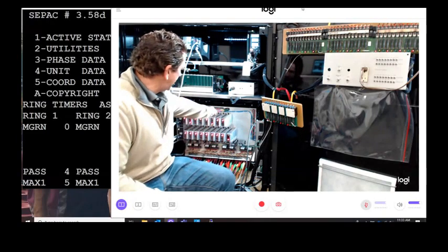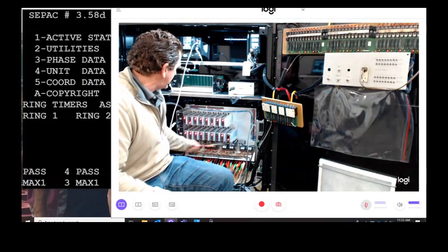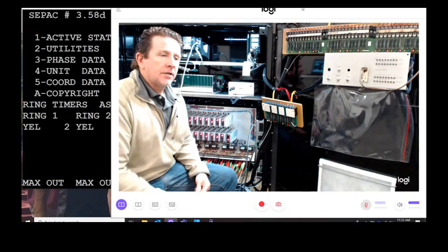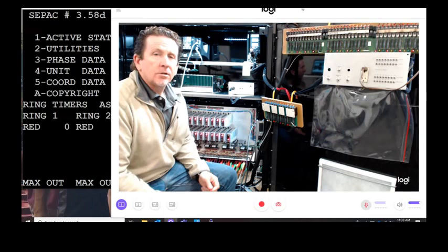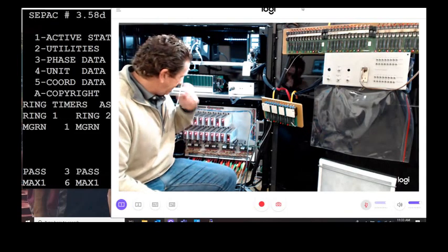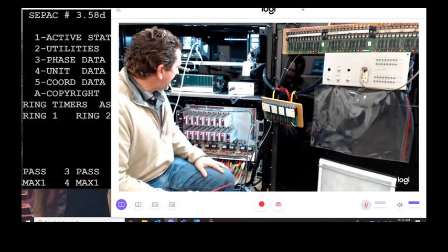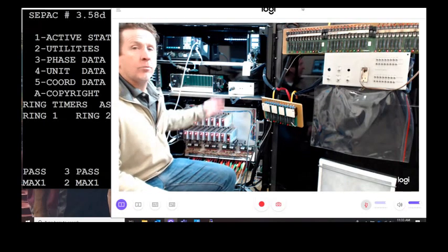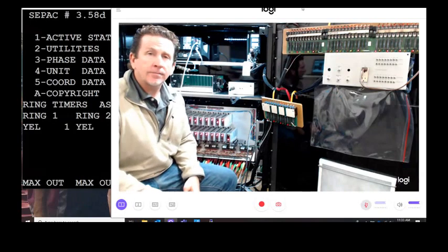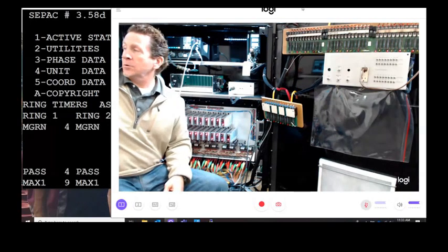So on the back panel, I have an L board, it's green, that goes down. We've burned out the runs on the circuit board, which were for 24 volts or logic ground, and basically we had to replace that. So I can have a 24 volt problem without a 24 volt failure. If I get a 24 volt failure, it's going to be in my power supply. Okay, so that kind of goes with the 24 volt stuff.